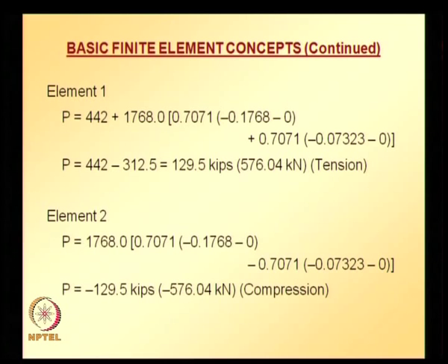And element 2, as I mentioned, is not going to have the P of t contribution, because there is no force fit for element 2. So, P of t is 0. The calculations were similar to what we have seen in the earlier class, where there is no force fit, and it turns out that the force in element 2 is negative, which means it is compressive.